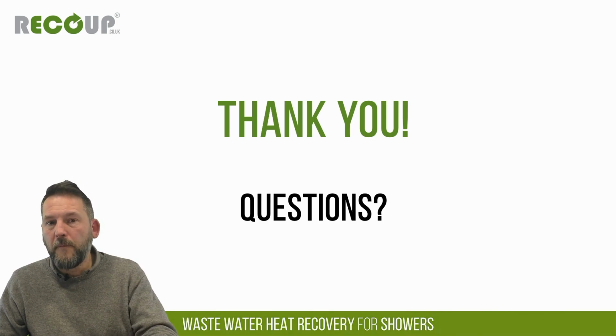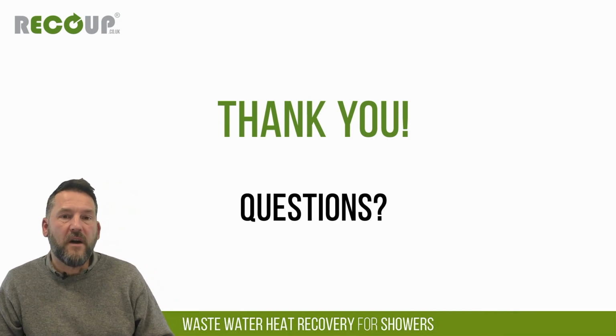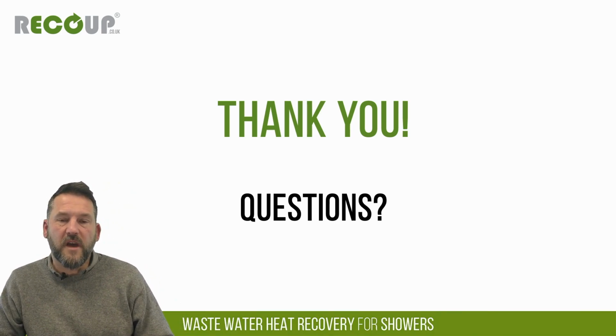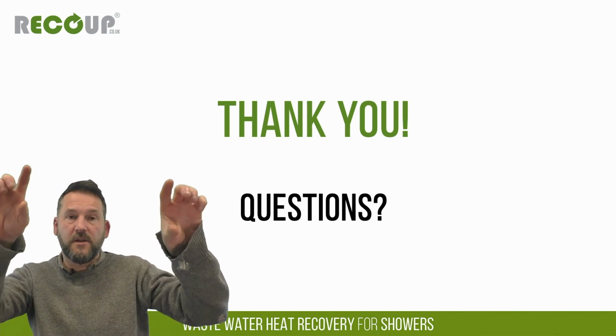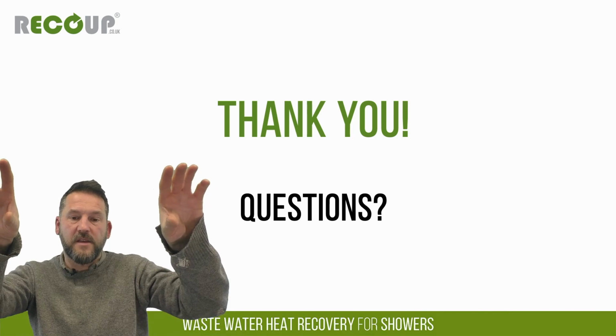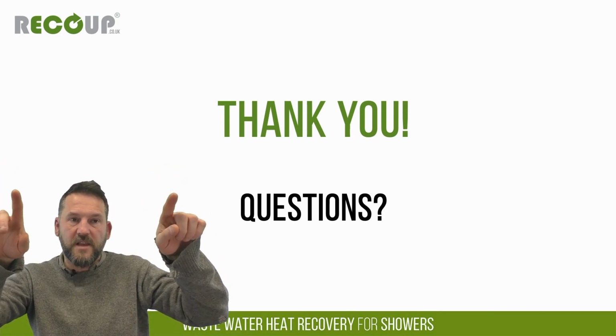One last question just popped through, which is quite a good one, which is how many showers can you run into a single pipe? Yeah, good question. It will depend on the total flow rate of the showers and the installation method. Total flow rate for the vertical pipe as System A is 16 litres per minute. So if we were looking to install a single pipe connected to a shower over bath and an ensuite, the total flow rate of System A would need to be 16 litres per minute, so 2 8 litre per minute showers.